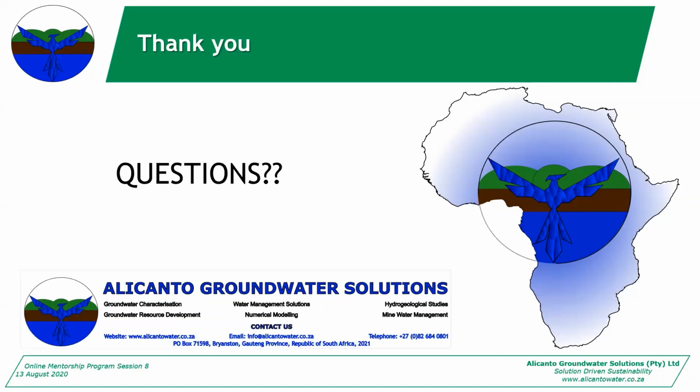No, I agree. And the one important thing that they really missed in that report in terms of interpolation, what that doesn't give you, is when you look at chemistry, it doesn't incorporate the natural attenuation, how the chemical constituents will maybe bind to the clays or something like that. It just says that the contaminants will keep on flowing and moving in that general direction or that general gradient. So that's one thing that interpolation lacks as well, is that interpretation of your hydraulic properties in your chemistry.